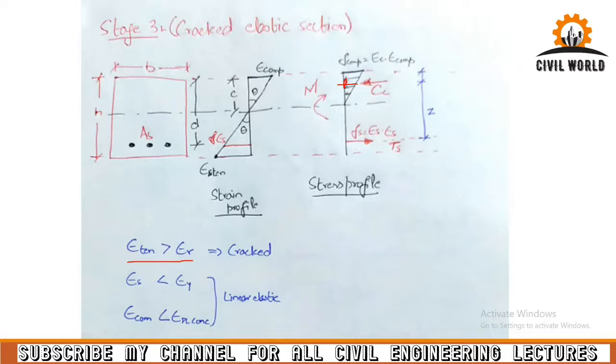Your summation of moment is equal to 0. So there is only one force other than this Cc, which is Ts. So Ts times z, which is the distance of this tensile force from this point, gives this moment. Or in another way, you can take the summation of moment at the other point, and your Cc times z is your moment capacity.